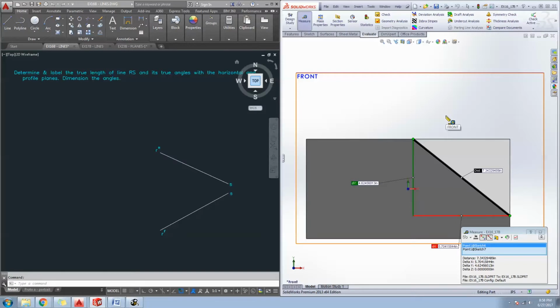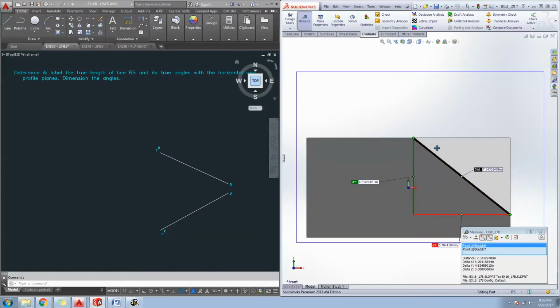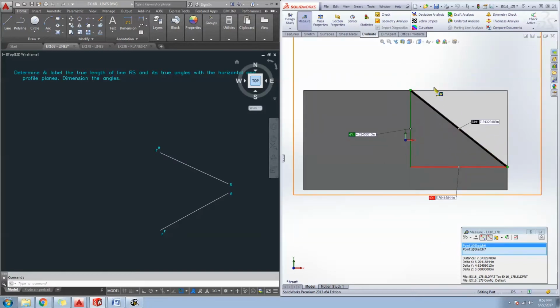So the last thing I want to draw your attention to with our whole measurement triangle is that we sort of have a right triangle Pythagoras thing going on here. And it makes sense that the measurements you're getting in other views are always shorter than the true length, because the true length represents the hypotenuse of that right triangle.